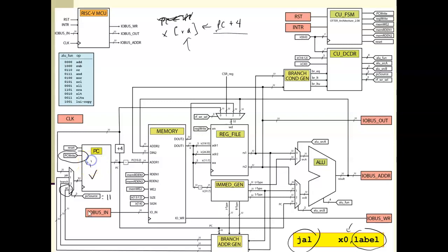So essentially, every single cycle, every single instruction, I'm always loading the PC write. Okay, essentially, I'm asserting the PC write. I'm loading a new value into the program counter, whether it be the next instruction, which is PC plus 4, or one of these other 3 values. These other 3 values handle the branches, particularly unconditional branches with the jumps, and just the branch is a generic branch. This instruction uses JAL, essentially means I just need to select the right PC source for this.